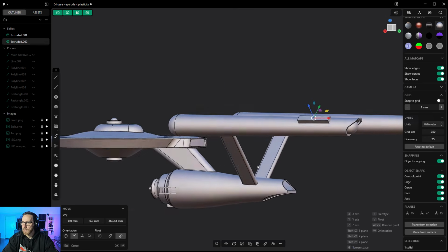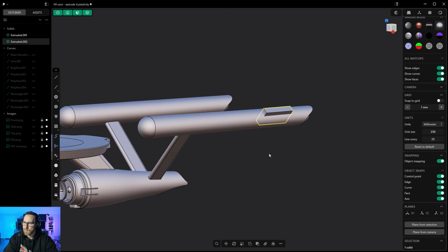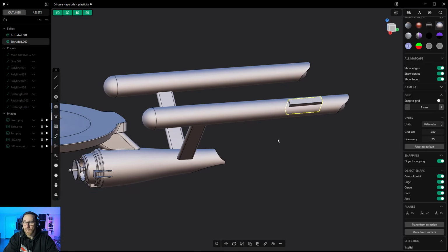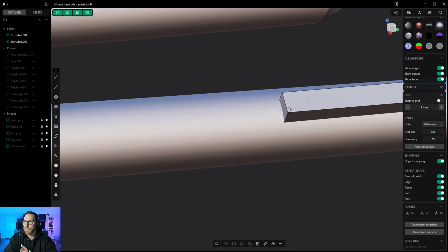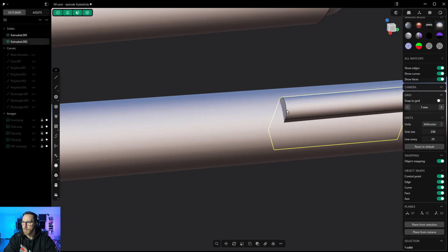And so this allows us to create that geometry relative to the view that we had, and then we can just simply move it to the right position. Now, again, you could create a temporary surface or a plane in that manner like we did as an example for these upright pieces. But sometimes this is going to be the quickest and easiest way. And then from here, I'm just going to go ahead and grab these corners, shift select, create a full round, and then maybe